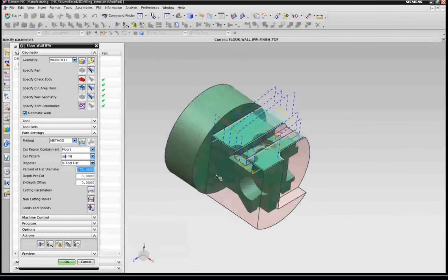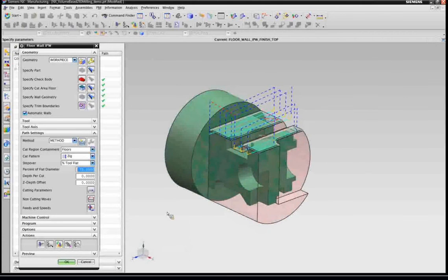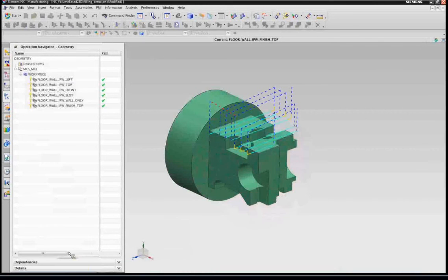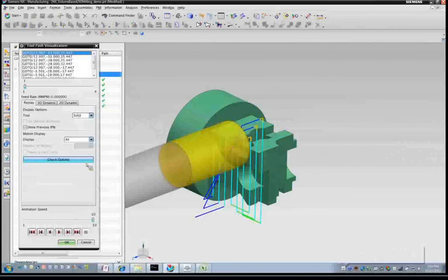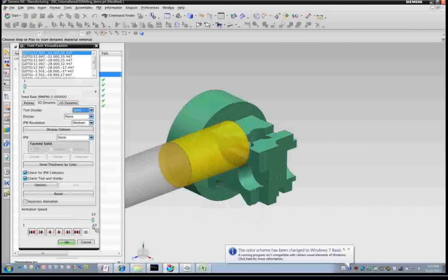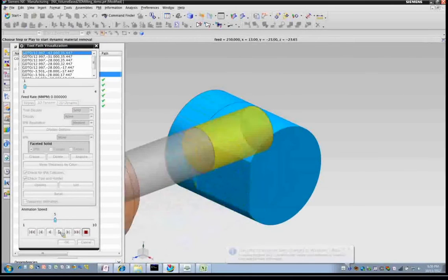We know that we've already cut the slot, so we're not going to put any toolpath on top of the slot. We're only going to cut the excess material that we still have to remove. So within 10-15 minutes, I actually created these 6 operations. I'll do a verify of my toolpath to show you what we've done. I want to show you briefly what we've accomplished with those 5 operations, and you'll see my entire toolpath.